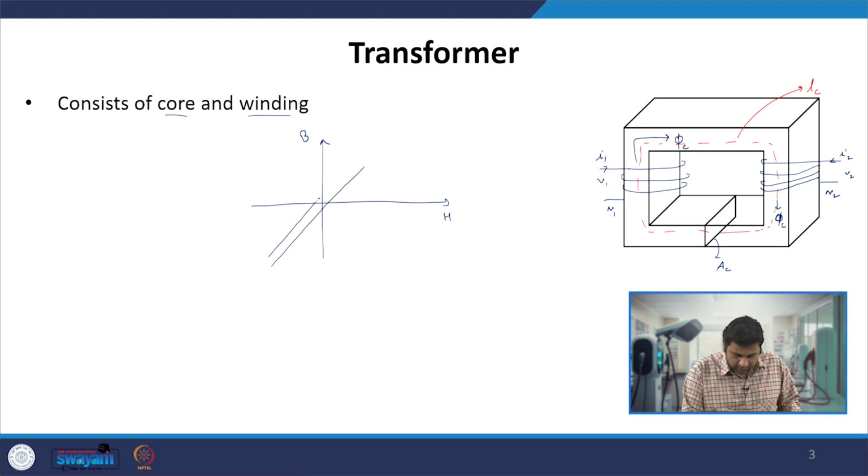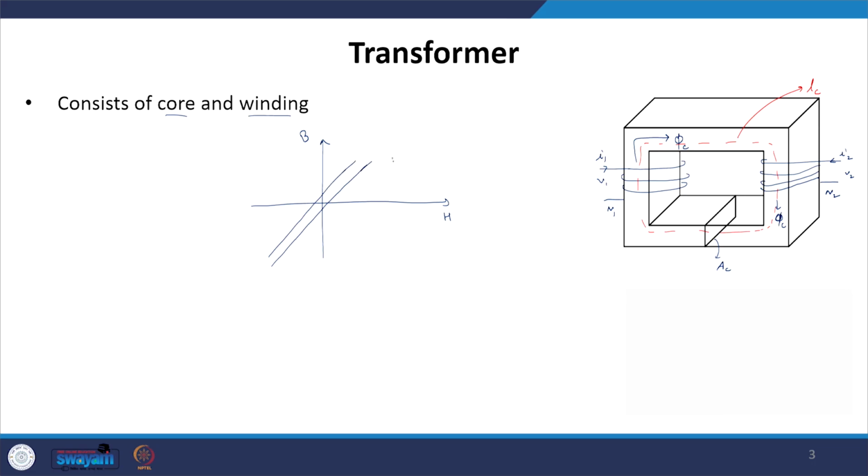where, what happens the moment you increase the external magnetic field is that more and more magnetic domains align themselves, that is, the net flux produced in the core increases. There is a point when almost all the magnetic domains align themselves, and that is when the core gets saturated, or you can say the flux in the core reaches its maximum value. That is why after a certain point we see no increase in the net magnetic flux density, even though the external magnetic field is increasing.